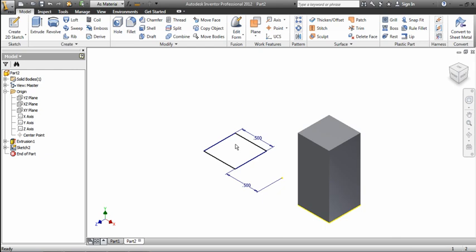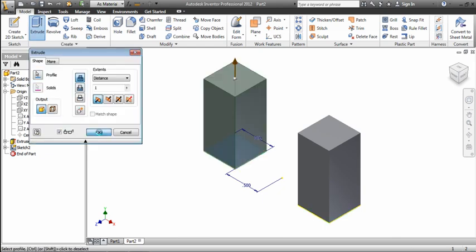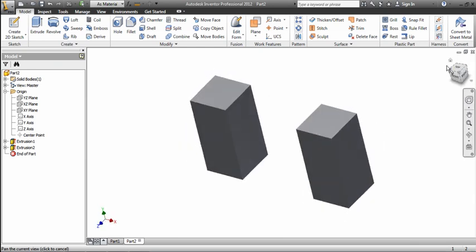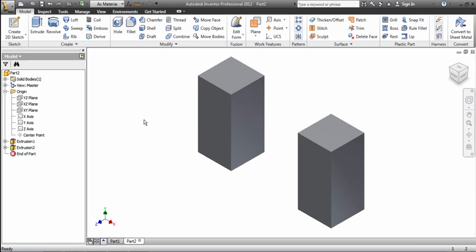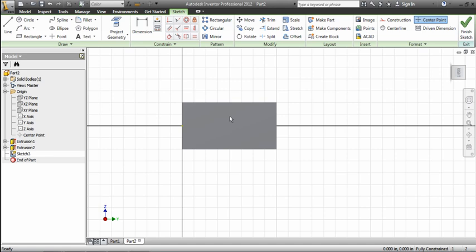And I'm going to extrude this guy as well, 1 inch. Alright. Very good. Now, I'm going to make a third sketch, and I'm going to do it on the YZ plane, the one that intersects these two. And I'm going to hit F7 so I can see through this material. Now I can see the actual sketch area that I'm going to draw on.